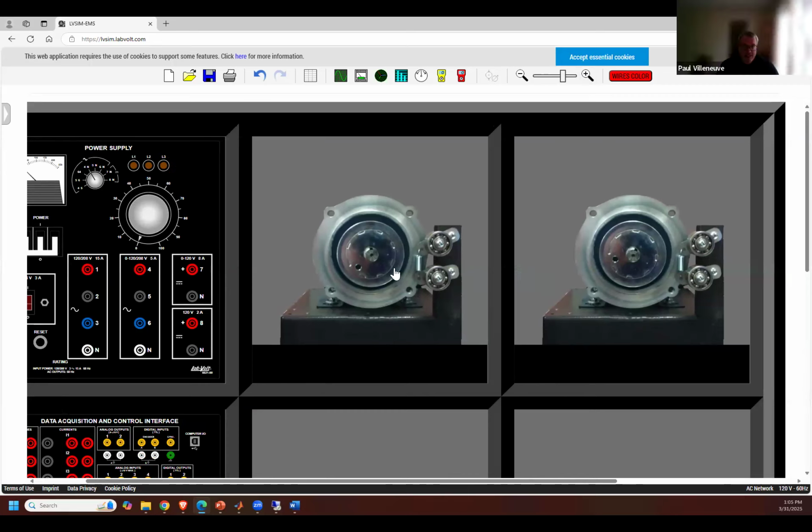That's exactly right. It's a belt tensioner, because if you just ran a belt from here to here, the only way to keep tension on the belt would be to eventually relocate and pull these motors further apart to make tension.